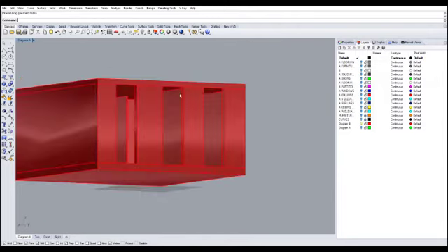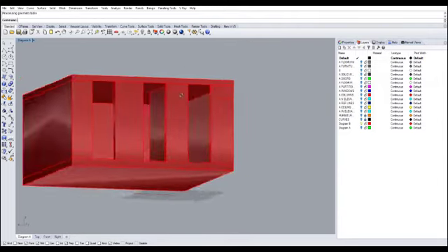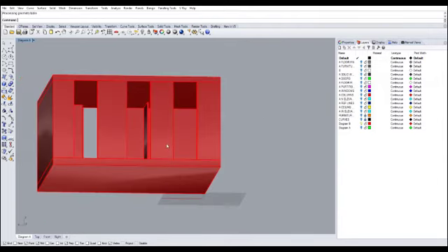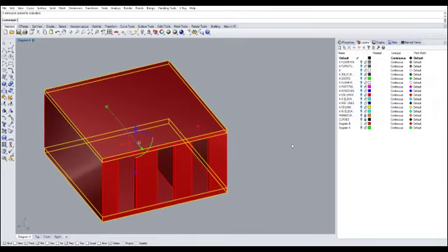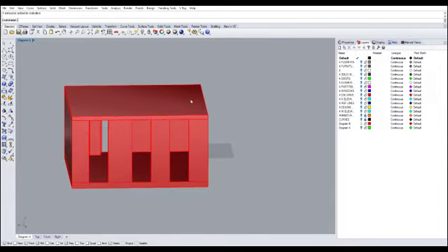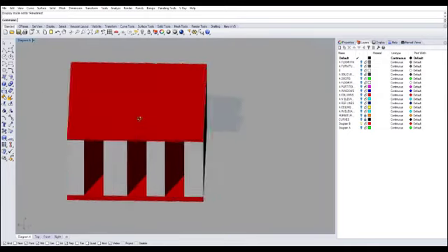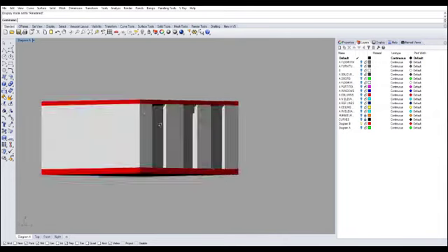Now we are ready to assign these diagram Toon shaders to our components in our building. So let's apply to our ceiling first. That will be the color diagram 1. Let's just go through it, 1, 2, 3. To see the preview of the render, of course, you have to go back to your render view. So our roof is red, or color diagram 1.